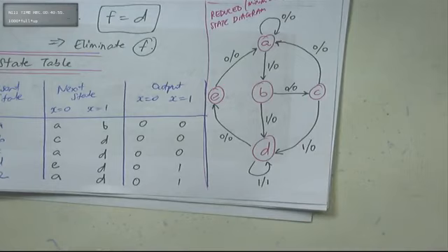Now a good question is, would you be able to do reduction in your state diagram? Check that out. Okay? In your project. Are you able to do reduction? Because obviously the larger the state diagram, the more the states, the more of a spider's web which you have to deal with in terms of your state table, the transitions, all these things, right? But if it's smaller and a cleaner state diagram, you have much more easier access. Yeah? You get what I'm saying? All right. Okay.